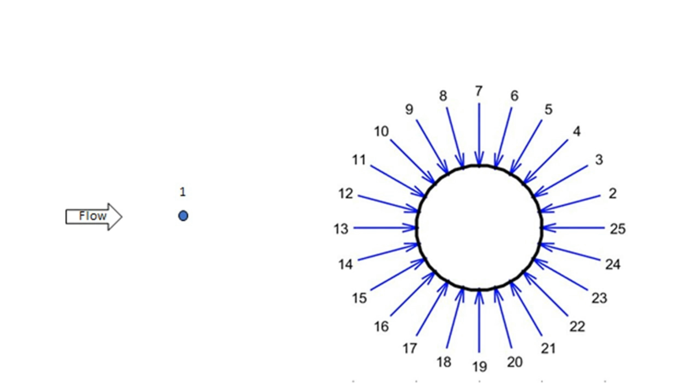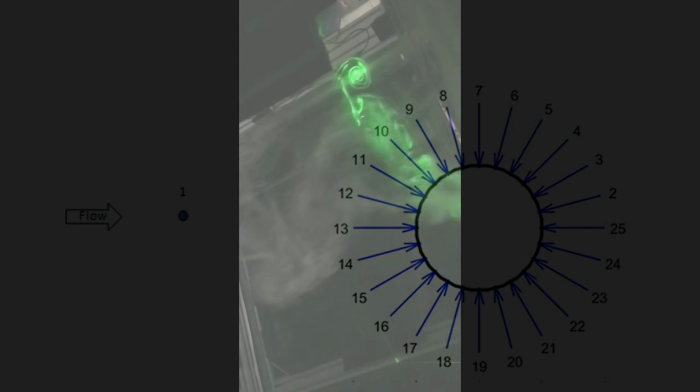Static pressure readings are difficult to make because disturbance of the pressure ports can alter the results, and they should be parallel to the flow direction instead of at varying angles. This lab assumed the flow was only 2-dimensional, but this assumption is not realistic since the air being pulled into the test section is from various angles and directions. Flow in the third direction could also alter the results for lift and drag forces.